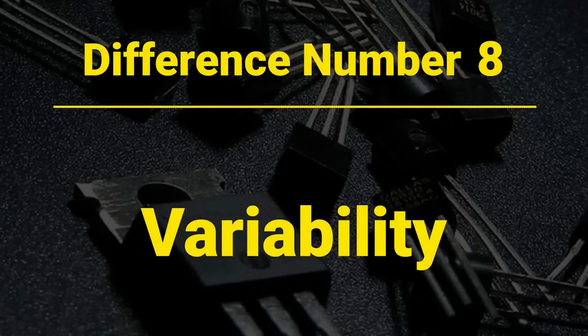Because of lower on resistance of a MOSFET compared to saturation voltage of a BJT, a MOSFET when fully turned on will act like a resistor with very tiny resistance. For modern power MOSFETs, the RDS(on) can be in milliohm range or even sub-milliohm, and this will make them a much better choice for high current applications. Anyway, the next item in the list is difference number 8, variability.